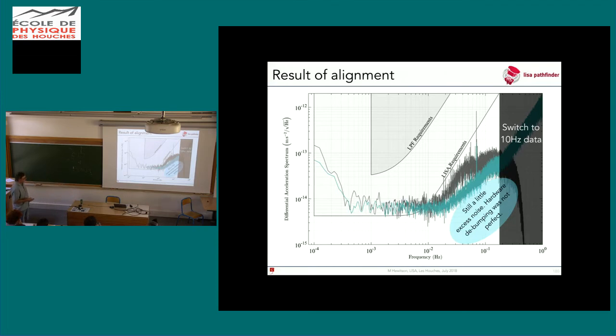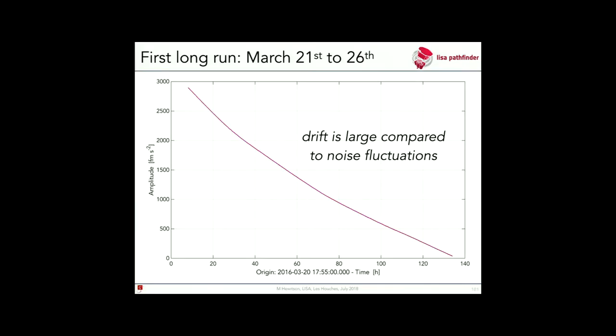So we had to do a lot more work to do that. In the end, it turns out it's easier to do it using measurements of these angular motions and just subtracting them. You can do that a little bit better. The reason why you prefer not to do that is the measurements of the angular motions are also noisy. They contain measurement noise, and the measurement noise is not coupling through this. So when you use measurements to correct it, you add measurement noise back in. And so that's why it's always better to do things in hardware if you can.